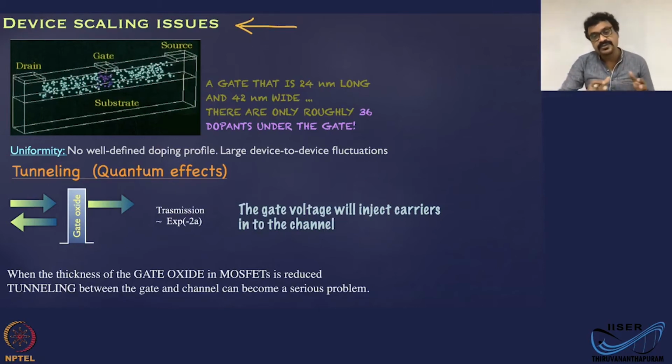Remember, as you increase the number of transistors or reduce their size, you are reducing the size of the active region. And remember, you have dopants in the system which are randomly distributed. Though they are uniform, they are also random. Okay, this is similar to what is shown in this illustration here.